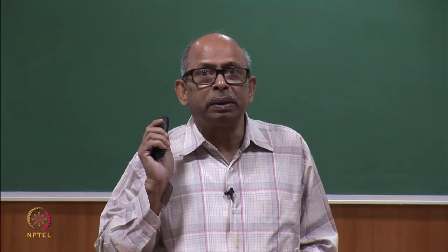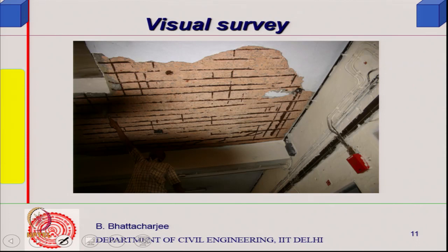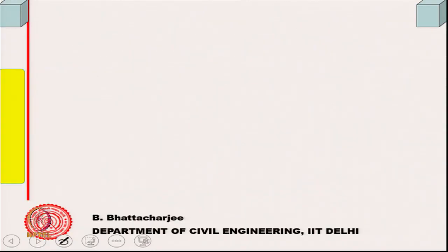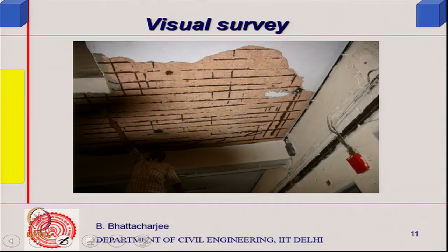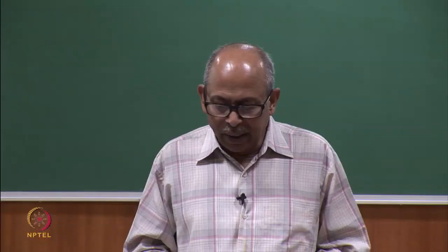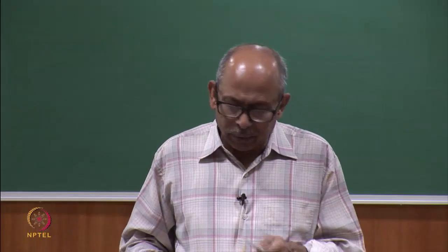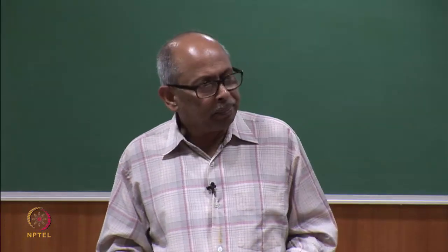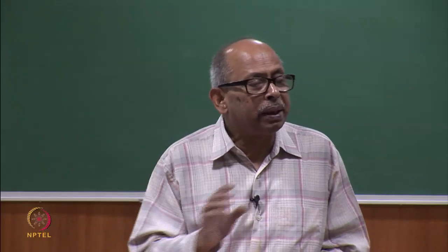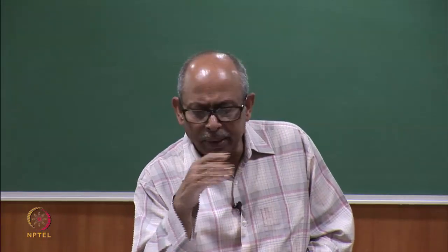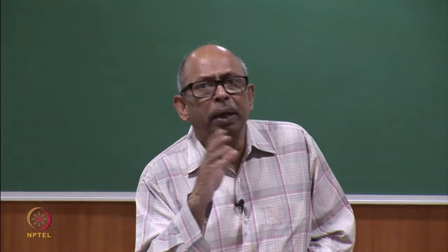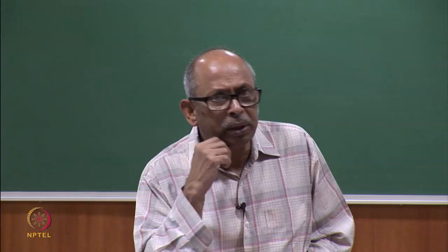For example, this case: rusting and cracking, a huge spalling. So, this will fall into the category of actually the last one, LG1, large general all over the area, 1. And this you will find in many places actually. So, one can do this kind of thing. I possibly have some case studies, I will look into it, then look into some of those. So, one aspect that I am saying is that you can use the anticipated state matrix, and these can be generated or are available for most of the types of defects or distresses you are likely to find.